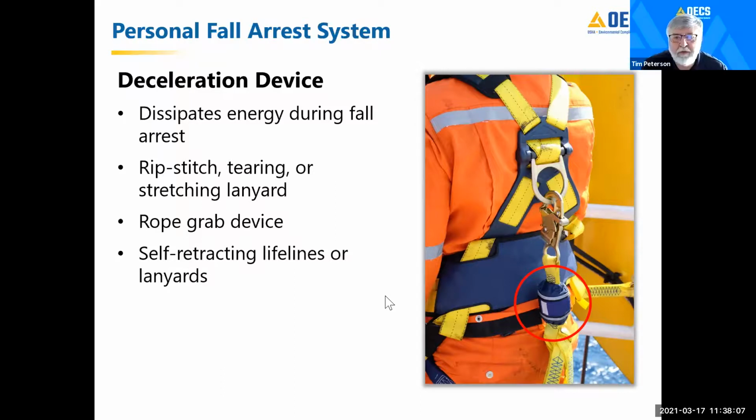And can a general contractor or an owner make certain requirements of what they will or will not allow for fall protection on a job site? They absolutely can. I can tell you that some of the general contractors in town actually require fall protection to be used when you're working in the scissors lift. And the standard does not require fall protection in the scissors lift. But for those GCs or construction management firms that do require it, you have to wear it.